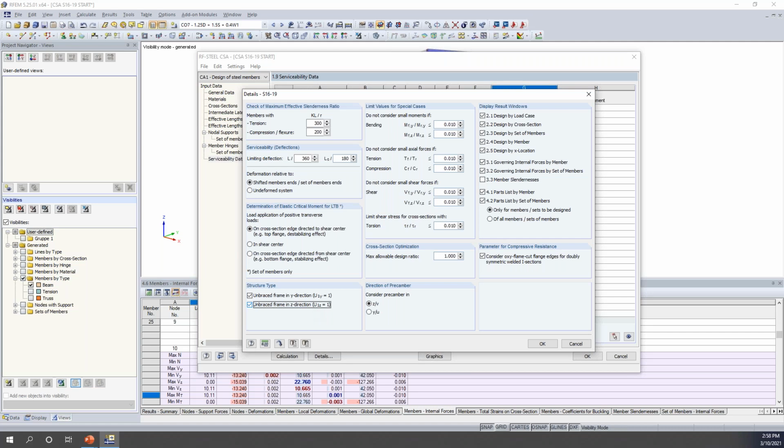There are also some other requirements within the code that if we're using the simplified stability method, forget Annex O, you also can set this use of one factor equal to 1.0 for unbraced frames, again, according to clause 13.8. So just something to keep in mind. But remember, we are taking into consideration P little delta. We are designing according to Annex O2 stability requirements, so we can leave this option checked.